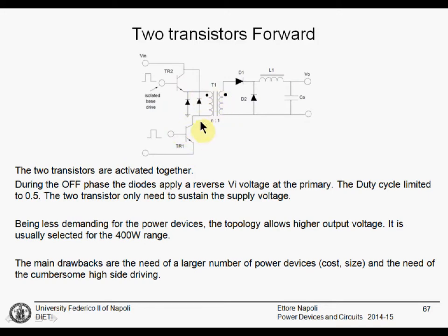While the current flows, it is charging the magnetizing inductance, obviously, and there is a current and energy transfer on the other side. Up to this point, almost no difference with what we studied for the forward converter. The only difference is another on-state voltage drop on the upper transistor, with some added energy losses. But in principle, no real differences.